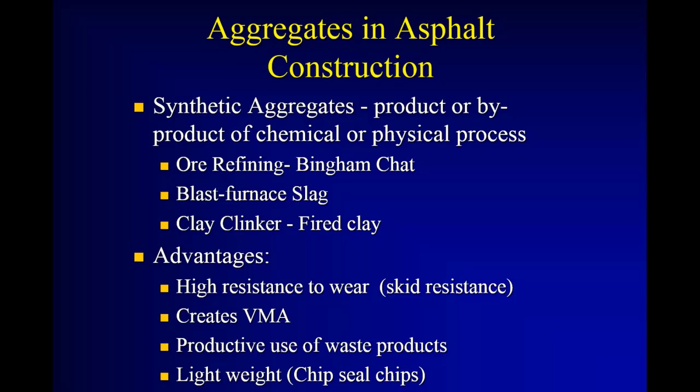In fact, if you put it in your hand and rub it too much, if you didn't grow up on a dairy farm or do much manual labor, it's going to cut your hands up pretty good. And so this blast furnace slag is very common, getting kind of short as well, believe it or not, because they use so much of it for wearing courses in the Chicago, upper Indiana area. High skid resistance, the more texture and the more angular material it creates, this VMA, voids in mineral aggregate, which we'll talk about here, and it's using a waste product.